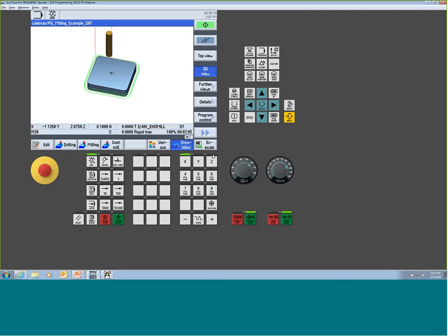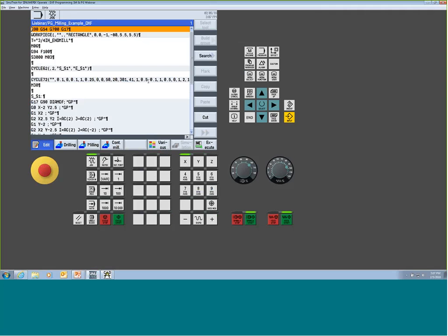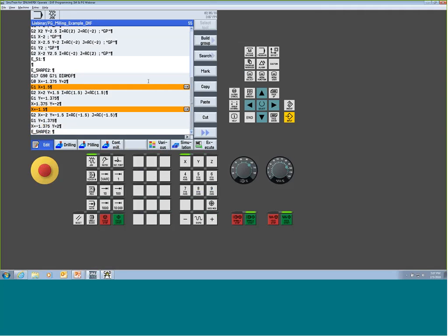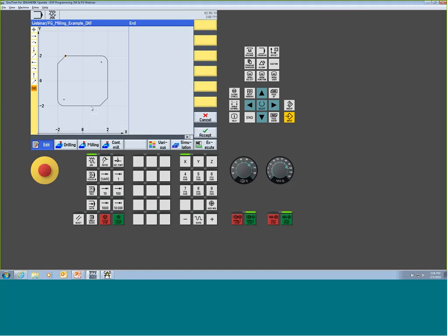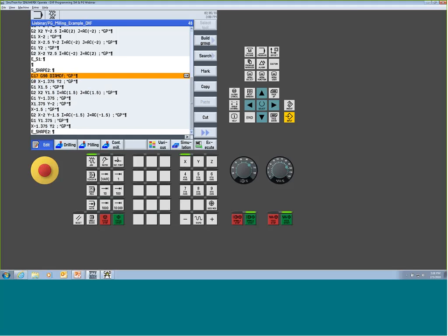If we go back to the program, go back to Program Manager and reopen it, now I'm expecting to see my, I thought I typed that properly. Okay. Did I see this G71? That was that little scenario I was saying to watch for. The system doesn't necessarily know, and being a European-based control, a lot of times we default things to be G71. So when it first builds this, it's defaulting to potentially metric. If you simply open the feature and save it, it removes the G71, and now I don't have an issue of it scaling or showing the wrong size. So you do want to be careful with that. If it looks like it's coming in really small or really big, obviously the scale's wrong, just open it up, save it, and that default G71 gets stripped out. We're doing that at the control level.